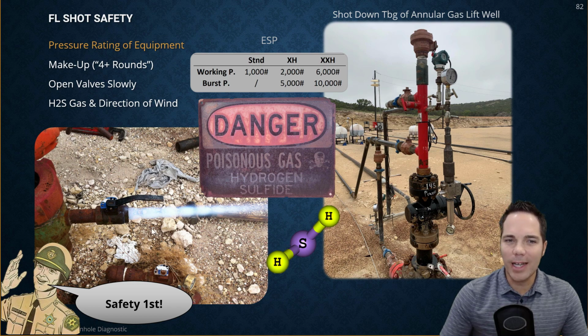You don't want to breathe in natural gas in general, right? So I basically take the principle that I don't want to breathe any of this in. And so once you shut off the well and you're bleeding off the gas, go upwind, or at least take a deep breath and move around a little bit, get a little bit away from it, let it bleed down before you put your head back down to take your gun off.